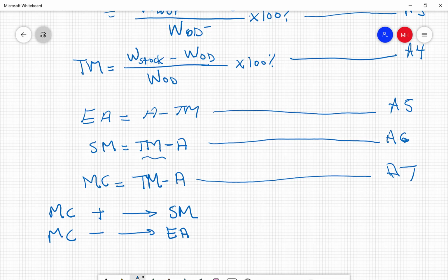We need to be familiar with these calculations, how to manipulate and handle these figures and numbers, so that when we do the mix design, we are able to decide whether to deduct water from the water-cement ratio we specify for the mix based on the aggregate moisture state, or add water depending on the aggregate moisture state. So this is very important to be familiar with. Go through these equations, become familiar with them, and, like I said, be able to manipulate and handle these equations and terms for that purpose.